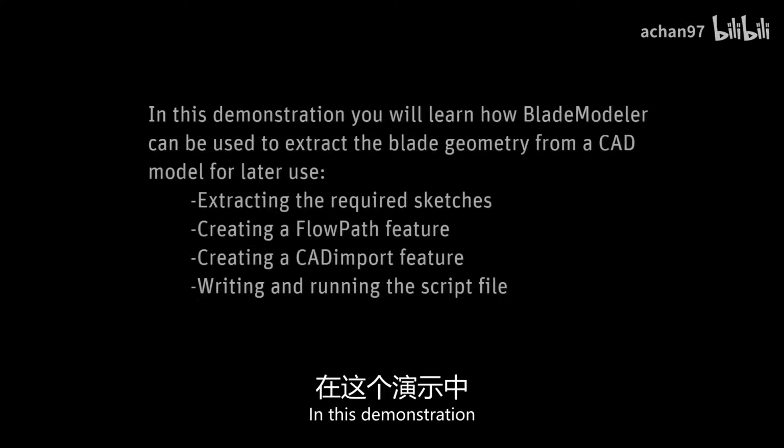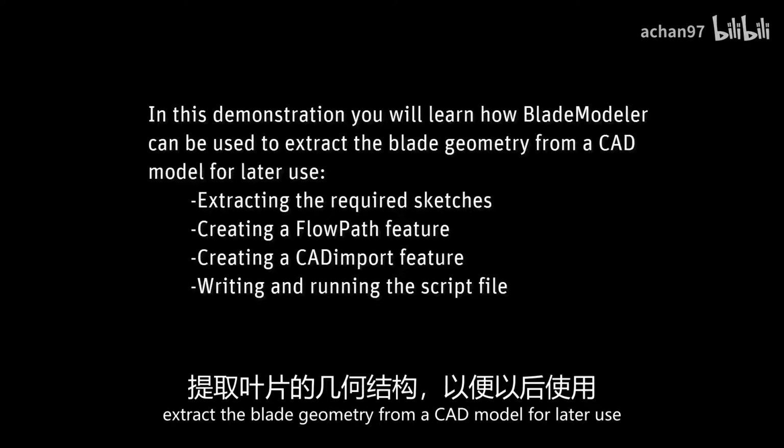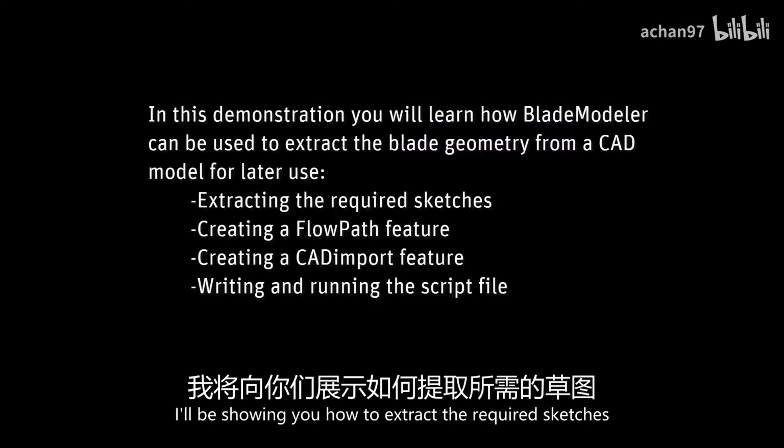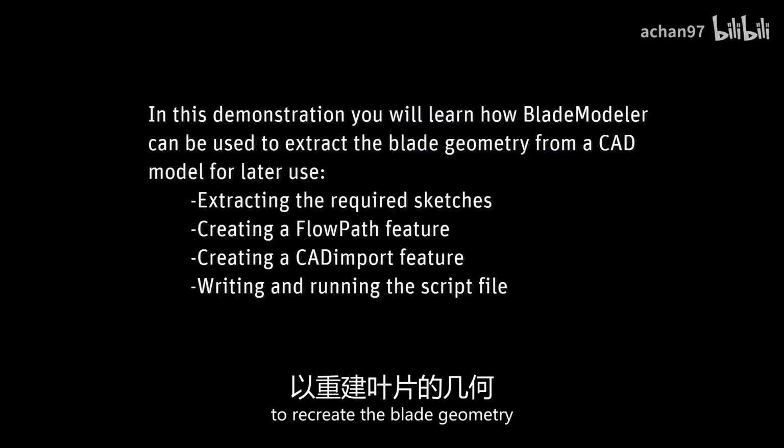In this demonstration, you'll learn how BladeModeler can be used to extract the blade geometry from a CAD model for later use. I'll be showing you how to extract the required sketches, how to create a flow path feature and a CAD import feature, and how to write and run the script file to recreate the blade geometry.